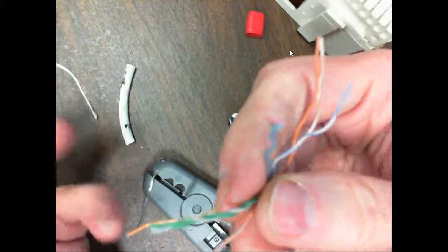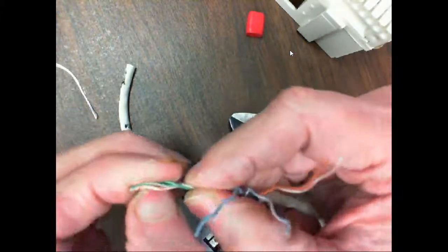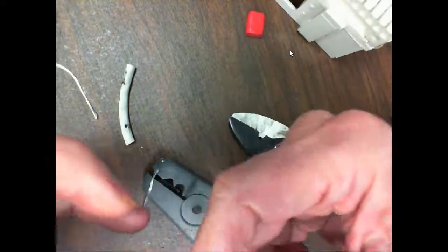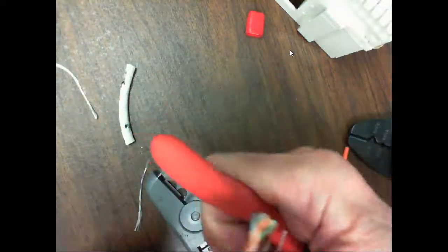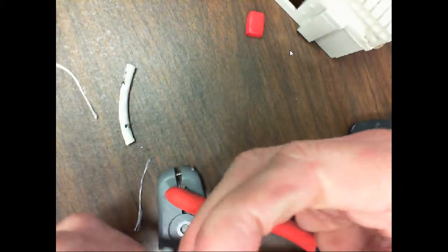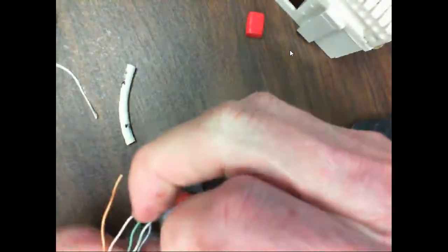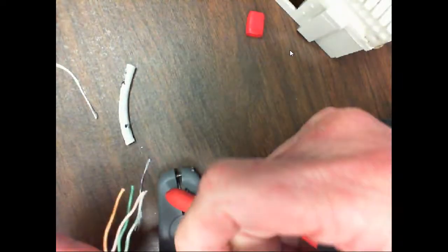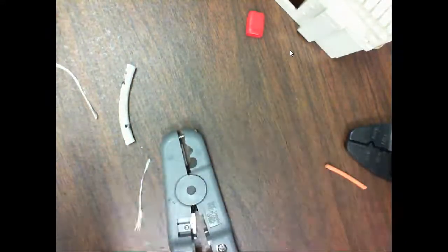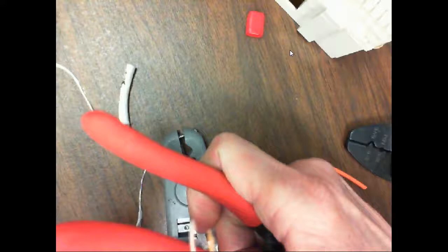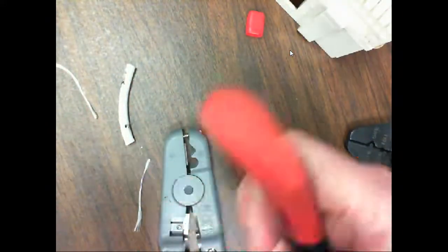Well, we're going to cut off all this. Yeah, if I was to crimp it down there, but I've seen people do this. I've seen people crimp like this. So what we do now is usually I get something like this, and then I lay this on here, and then I come up here and start pulling on it to do what? Straighten it out, because if you got it twisted like that, it's not going to go into it. Now, when you cut these, this is where it becomes critical, where you want to cut these to a certain length. So y'all see how I'm doing this? I'm just doing this to do what? Straighten it out.